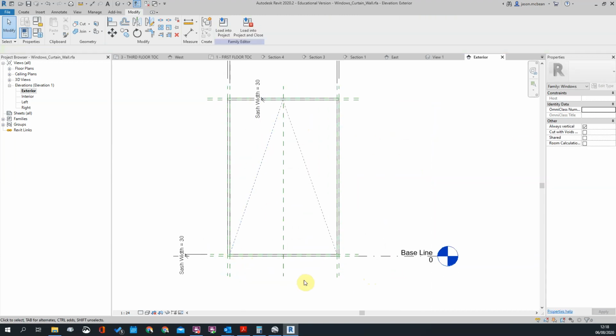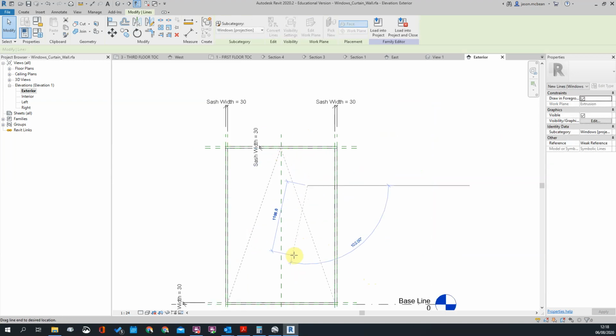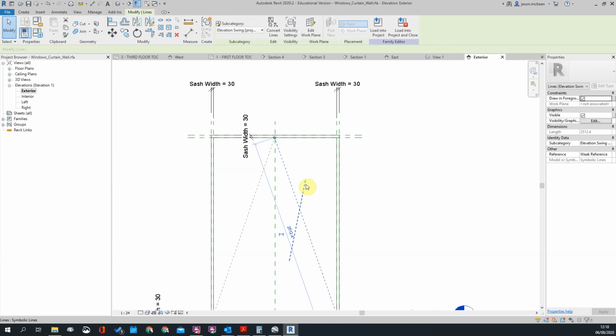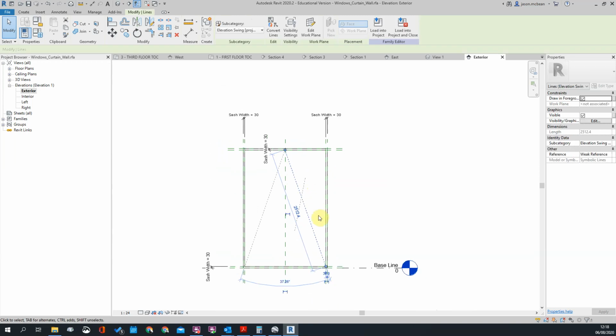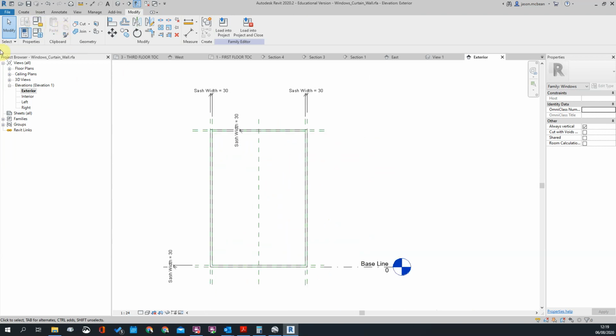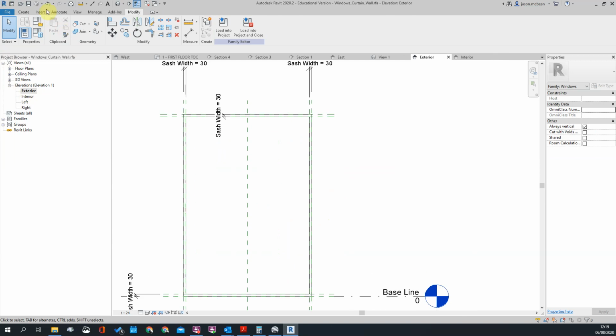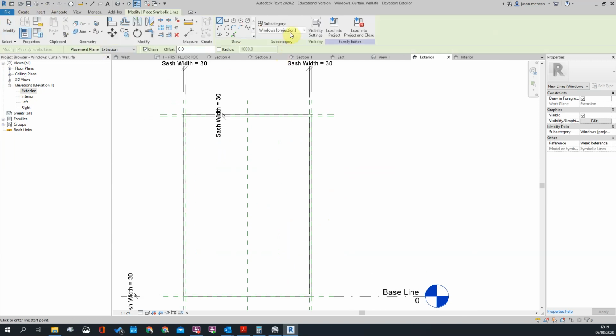These, however, work in the opposite direction. So I'm going to move this down this way. Okay, I'm going to switch these off because I want symbolic lines for this. So interior and exterior, they're going to be symbolic lines. Okay, so you're going to go and say create, annotate, symbolic line, and you're going to say window. This will be window swing, elevation swing, projection, or cut, it doesn't matter. So technically, these work in this direction.